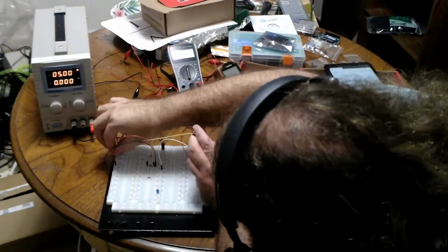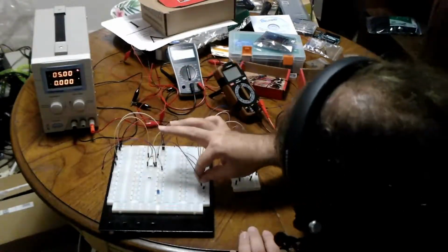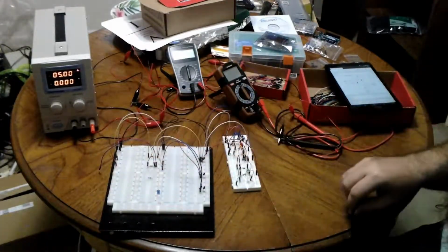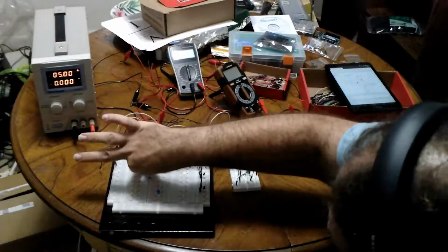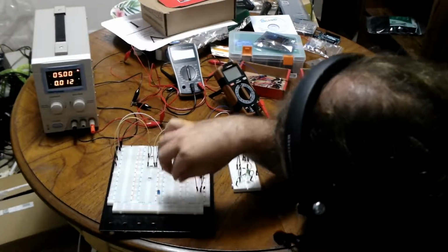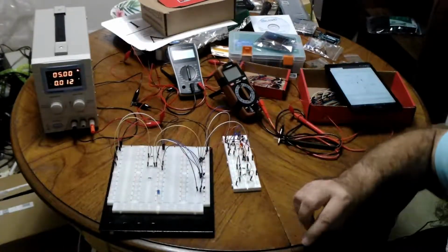Let's make our NOT gate. So we have positive power to a resistor, from that resistor to a third transistor, and from that transistor over to negative power. So there's our NOT gate. Now we need our input. The output of our NAND gate goes over to the base to emitter junction, not some other junction you might have been thinking of. But then, see, our current changed.